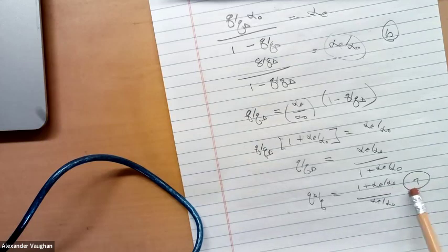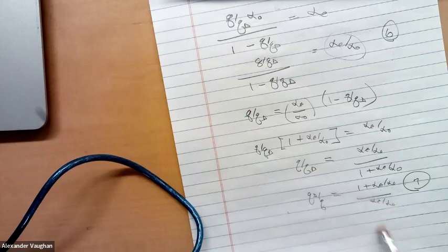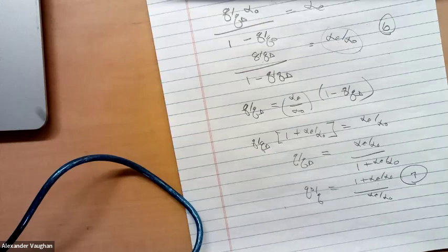In the divergence case, most people would say our math models are so good, we don't need to do a lot of wind tunnel testing on divergence per se. But in flutter, which is sort of the dynamic counterpart of divergence, it's still a matter of intense interest and technical challenge to use a concept like this to measure some dynamic response below the flutter condition to anticipate where flutter will really occur if we ever got there.